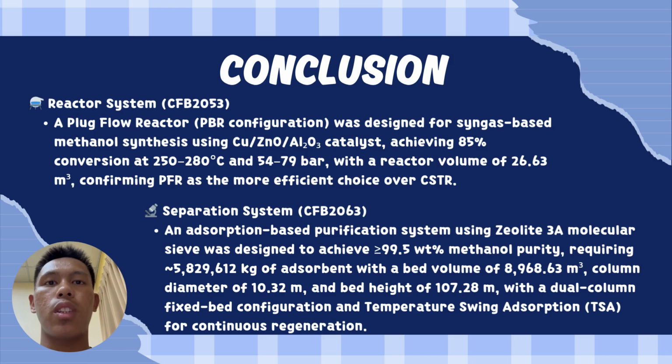For the separation system, using zeolite 3A molecular sieve, an adsorption-based purification system was designed to achieve more than 99.5 weight percent of methanol purity.